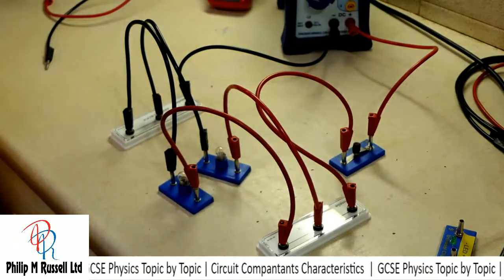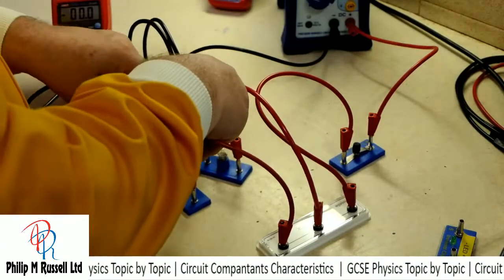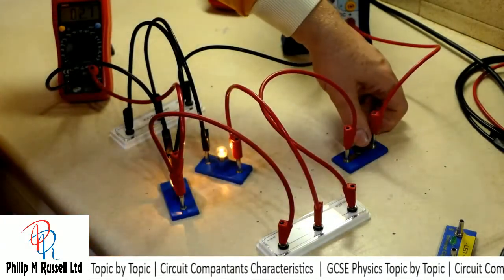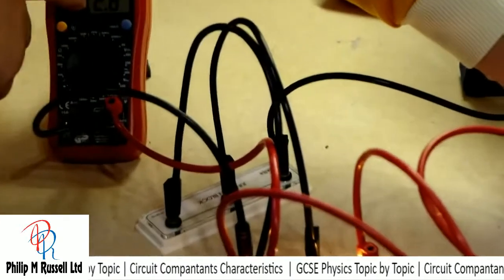If we put the voltmeter in across one of the bulbs, let's do the one at the bottom, then this should be reading about 3 volts. It's actually reading 2.8.